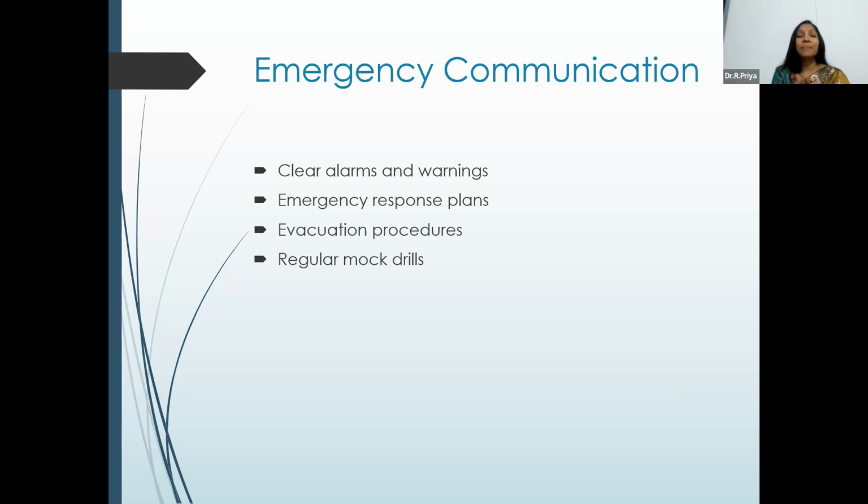It normally happens on the construction site, right? Emergency exits and distinct assembly points are marked. They help the workers evacuate safely during a fire or structural emergencies. Then regular mock drills test the effectiveness of emergency communications and preparedness. They help the engineers identify the gaps in communications and improve the response time.